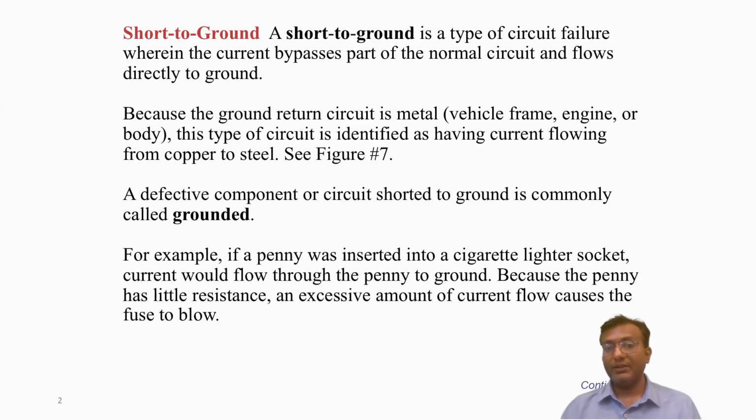Now, diagnosing high resistance can be very hard to spot because it may only show up when certain conditions are present, like high temperatures or vibration. The common causes include corrosion, loose terminals, and poor connection. A dim headlight may indicate high resistance in the wiring, reducing the current reaching the bulb.